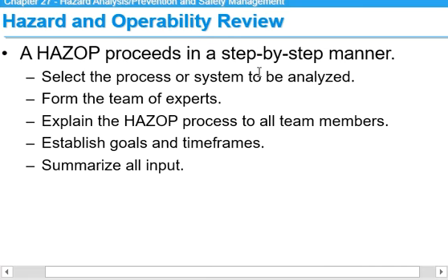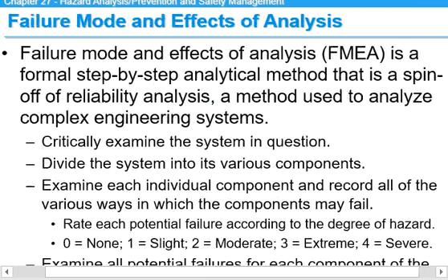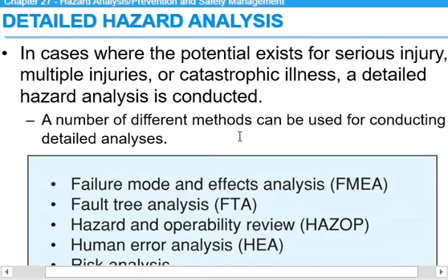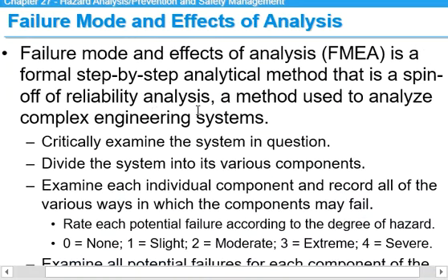You might have in it maybe a human factor, but it has to deal with the process as a completed process. The FMEA, if you go back to it, its job is to tell me, hey, where I might have a failure in the system, in which component, okay? The FMEA is to tell me where I might have a failure in one of the components of my system.